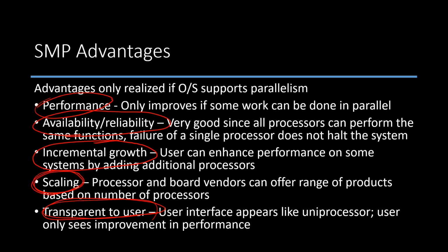What we were doing with the bootloader type code was just running on a single core, and it still looks like a single system. But when you installed your Raspbian operating system, multiple cores appeared and the operating system was able to define which of those cores a particular task got assigned to.